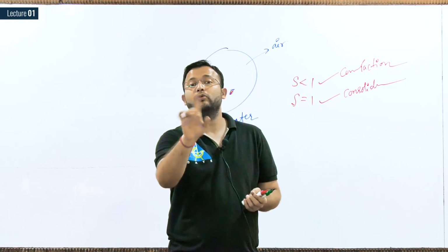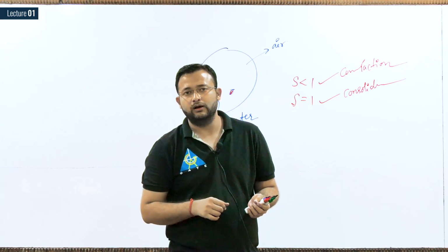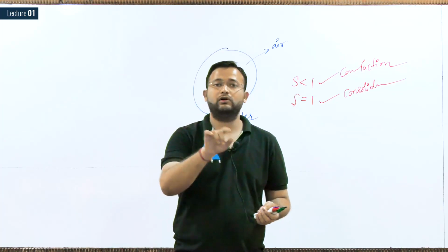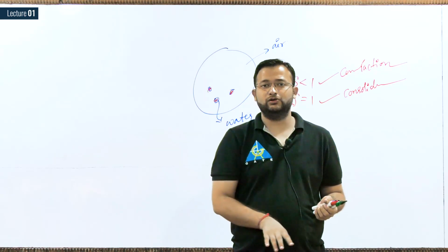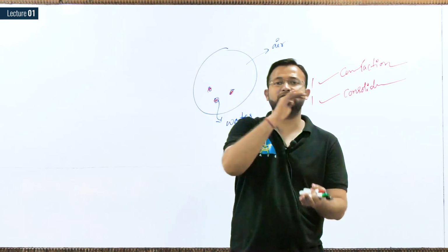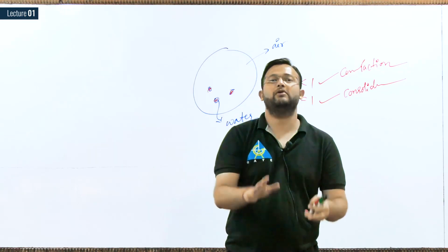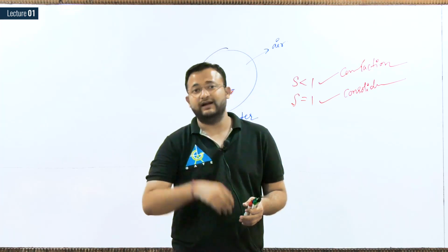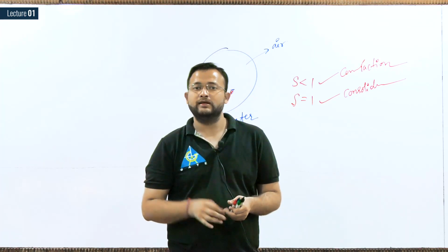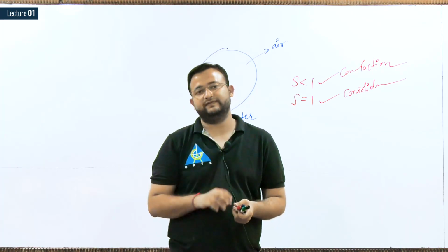So I do not want settlement of my footing, dear. If I do not want settlement of my footing, then before the construction, whatever settlement is possible, you perform it, means you perform your compaction process, so that when I construct the building, the settlement can occur only because of consolidation.